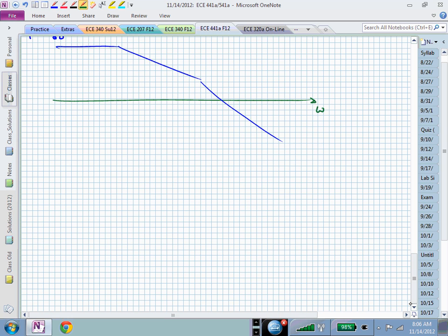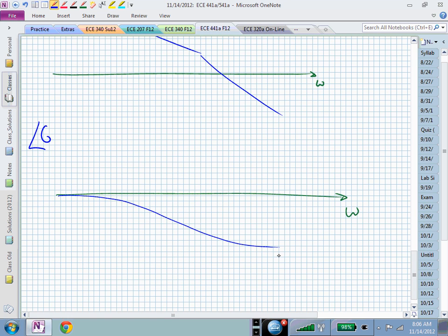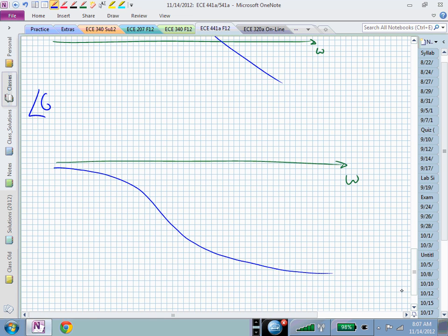The horizontal axis is usually logarithmic so that you can consolidate a lot of information in a less wide piece of paper, for example. Then corresponding to that magnitude plot, you also have the phase plot of that transfer function. And so these two can be read together. That's probably not a very good sketch, but you get the idea.